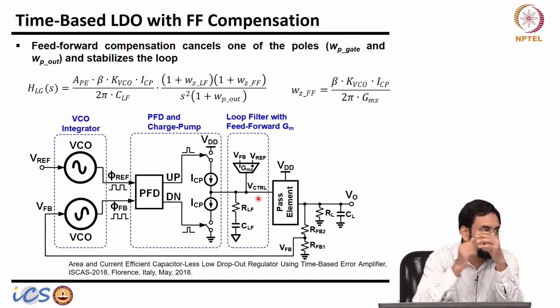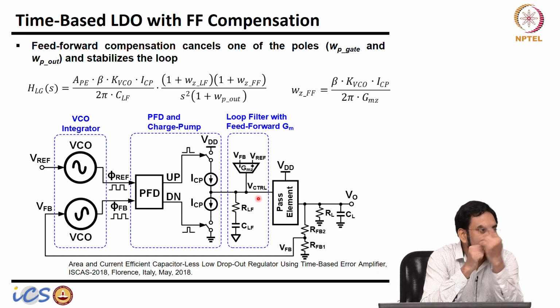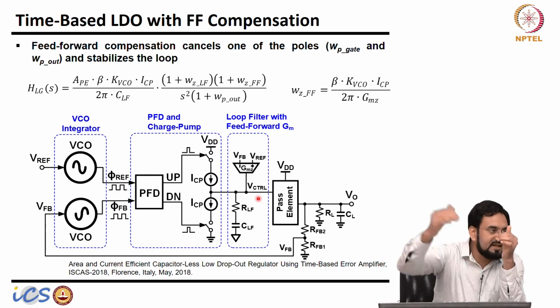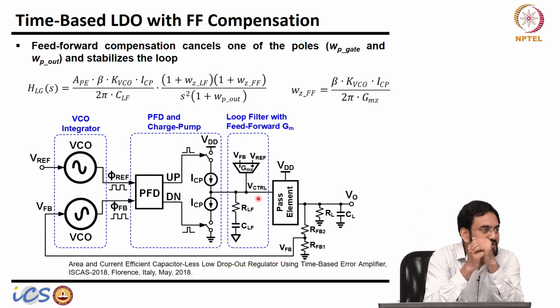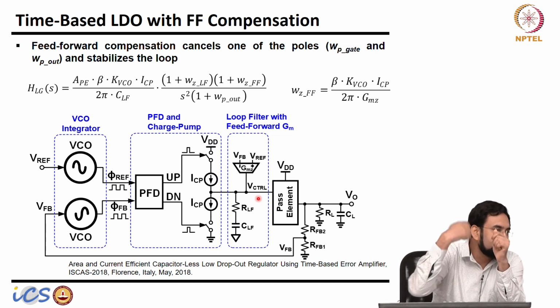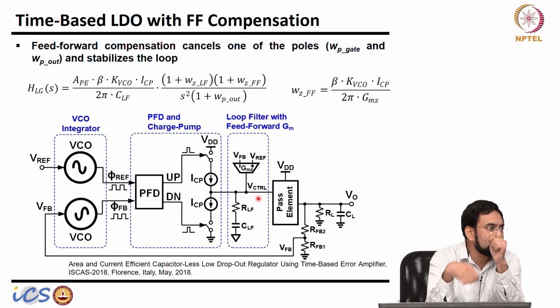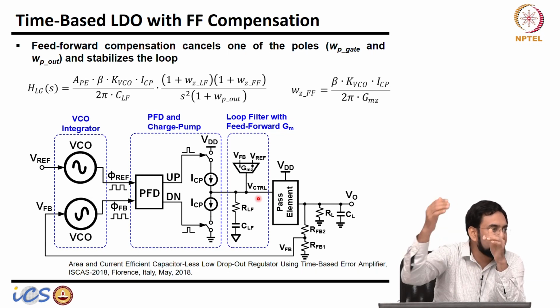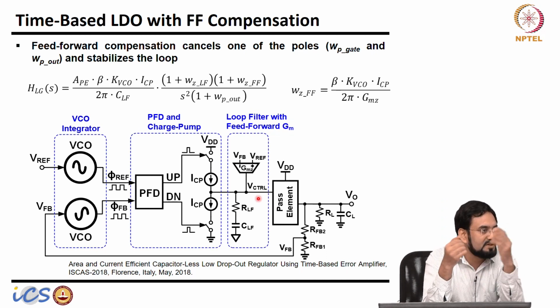Now let's say I have 10 phases, so each phase is carrying 1 milliamp, so I have to size one power FET for 1 milliamp only, and they are connected in parallel. Whenever my current requirement goes above 1 milliamp, only then I will turn on the second phase. When it goes more than 2 milliamp, I will turn on the third phase. That's how I will keep turning phases on and off as the load varies.